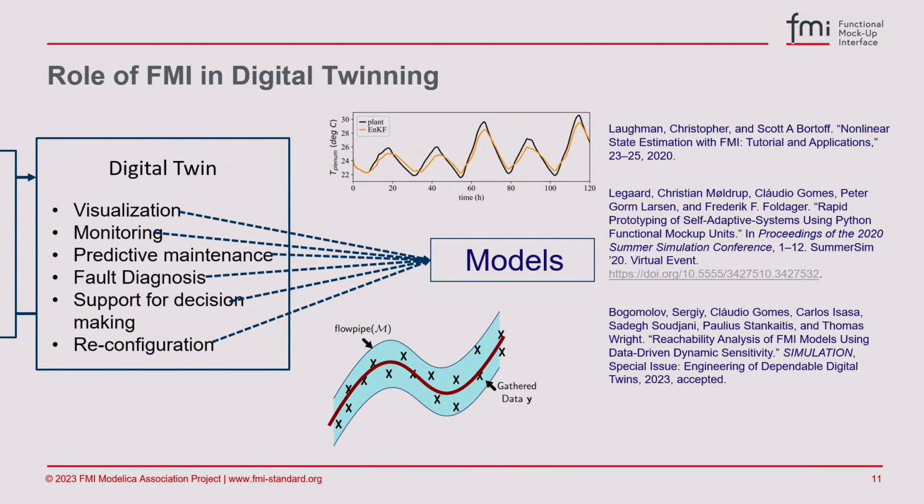You can do predictive maintenance, typically generating lots of data to train AI to detect degradation trends on your components. In the same way you can use models, therefore FMUs, to try and do fault diagnosis, because you can vary the parameters on these models to try and find a match between the model behavior and some faulty historical data. Hopefully the concrete valuation of parameters you have found will reflect what happened in the physical system, if you have a good enough model.